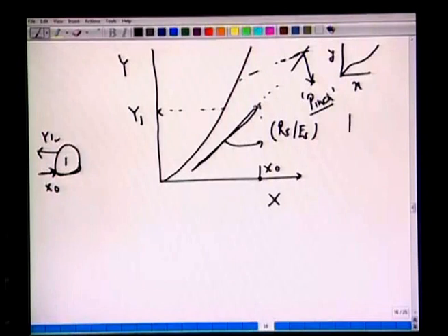In case of co-current, if you recall, we had the equilibrium curve like this, and we had the operating curve with the negative slope, which hits here, it reaches the equilibrium, all right, where we can say that two phases are in equilibrium. Here, notice the difference, we have this operating curve which has a positive slope, and still it's possible that in some cases this line may hit the equilibrium curve depending upon what type of system we have chosen, and wherever it happens we will have the pinch, zero driving force, and we might require a very infinitely large number of stages here. Now, let us get back to this.